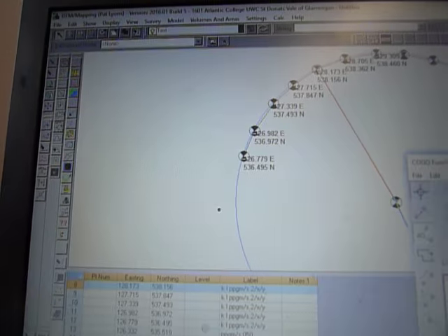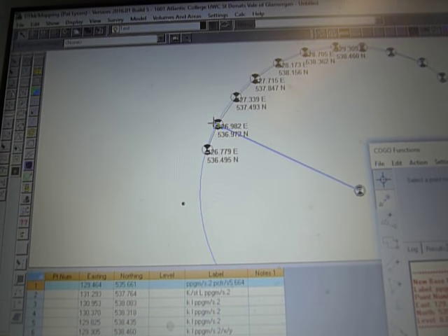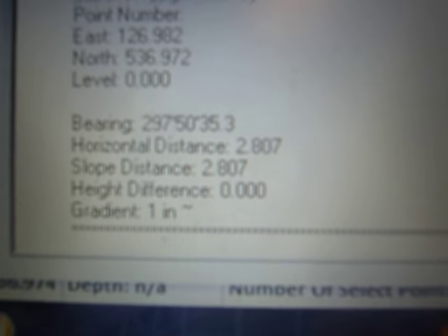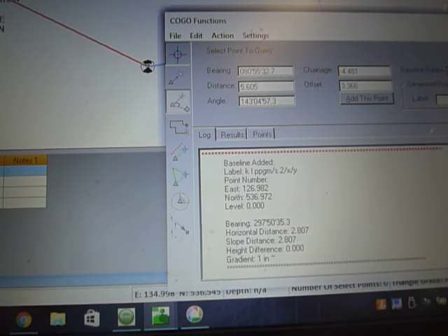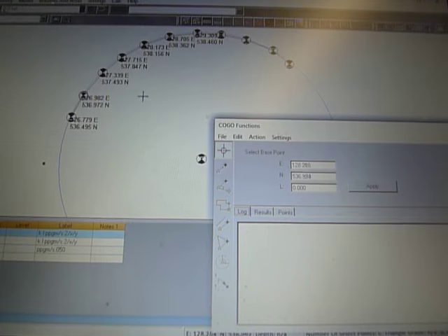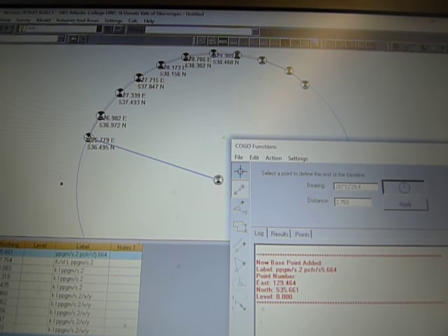Let's see if we've got one a bit worse. I'll click on here and I'll go to this one. Right, okay, so we've got another reading here, at these coordinates that we've surveyed on the shutter, and we've come out with 2807. So we've picked on some good readings here. We did have some readings as bad as 15 mil, and we've done a slight tweak to the 15 mil, and it's probably somewhere in the order of 10 mil now when we've poured, and we'll check after it's been poured, but I don't think there's going to be an easy way of moving these after it's been poured. You really have to get it right first of all, because when you're trying to move afterwards, you have the whole weight of concrete in there. So this particular reading here, we got 2812 and it's supposed to be 2812.